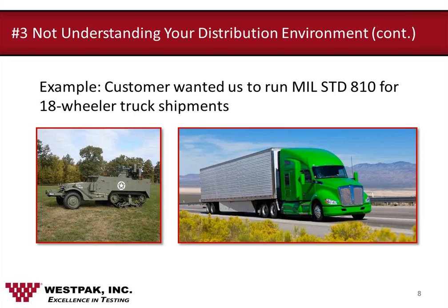So it's knowing which environment you're going to go through and making sure your test captures it. If you're going to do both, make sure it captures both. ASTM D4169, the new version 16, and ISTA 3A both capture both LTL and single parcel environments. If you know you're only going to go through a single parcel environment, I would recommend using ASTM D7386. Tim?